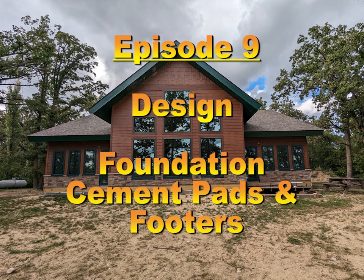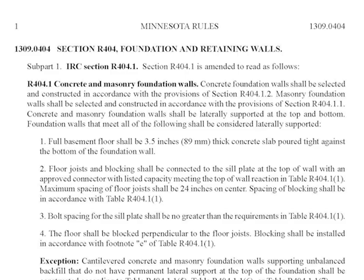Episode 9, Design, Foundation, Cement Pads, and Footers. Minnesota Code 1309.0404, Section R404, covers foundation and retaining walls. Now that I know my loads for every post down into the basement, I can distribute these loads into the soils below. This distribution is done through cement pads that are under the basement floor.